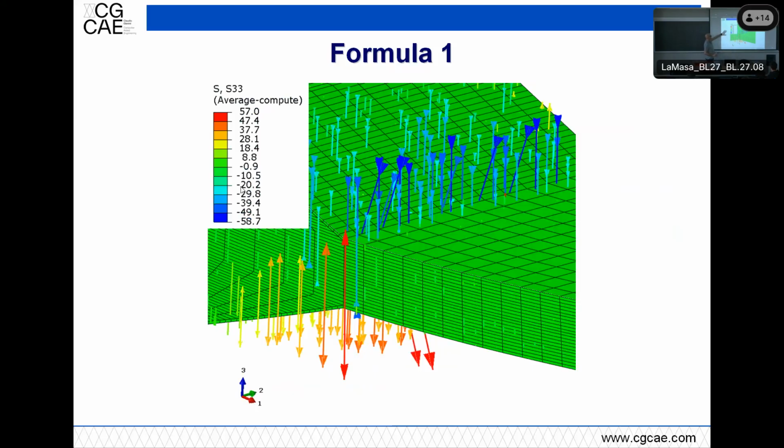And indeed, here we go from -60 to +60 megapascal, which for a resin, because normal to the lamination ply you have only the properties of a resin, there are no fibers along this area. There is a technique called Z-pinning, but it is forbidden in Formula One, where you place things normal to the lamination plane, which prevents this opening. 60 megapascal is by far too big.